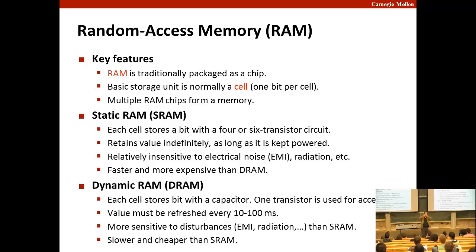Remember we talked about the fact that a processor has to be yay big, because if a processor gets bigger, the clock cycles as they propagate through will fall out of sync. Does that make sense? If I have a square wave and I send it over a short path and a long path, if they get to the same point by two different paths, they're not in sync anymore. And so even with all the money in the world, there's only so big we can make a processor. Because if we get bigger than that, now we have timing problems.